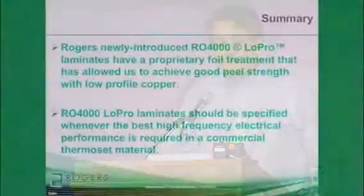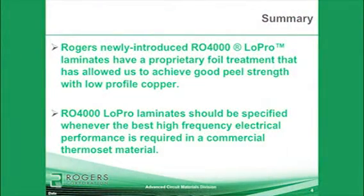And for all of these reasons, Rogers has newly introduced the RO4000 Low Pro laminates, which have a proprietary foil treatment that has allowed us to achieve good peel strength with low profile copper. RO4000 Low Pro laminate should be specified whenever the best high frequency electrical performance is required in a commercial thermoset material. First, a little background on copper foil technologies.